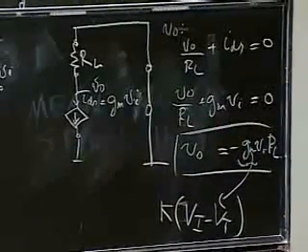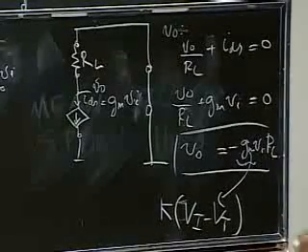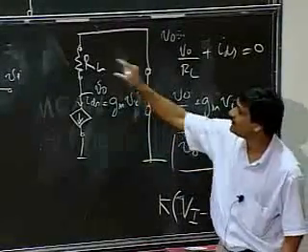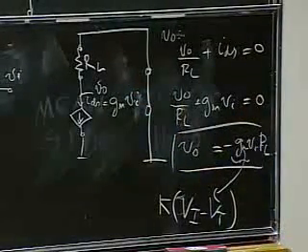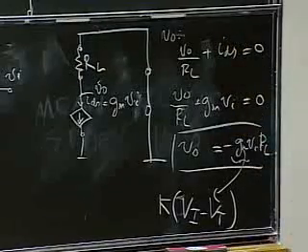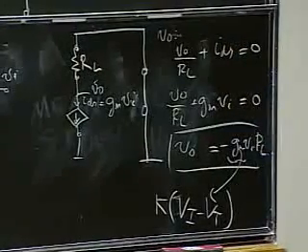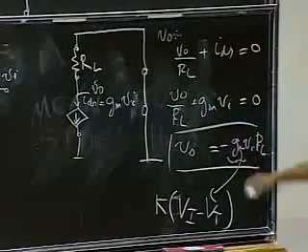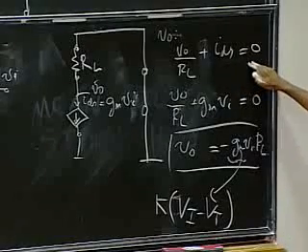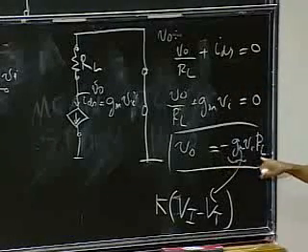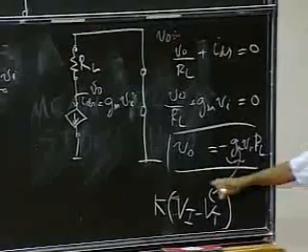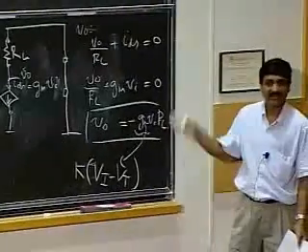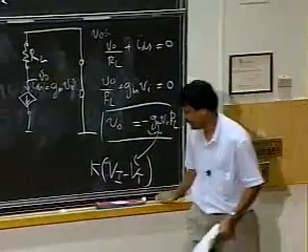We are done. Okay? So what have we here? I created a linear circuit which simply comprised small signal models for each of my big elements. And then I simply did a straightforward linear analysis using any one of the linear techniques I knew about. This is simple enough, so I applied the node method. And I got the equation at this node, simplified it, and I directly got the answer. So in 1 or 2 steps, I directly gave you the output as a function of the input. Okay? It can't get any simpler. Thank you.